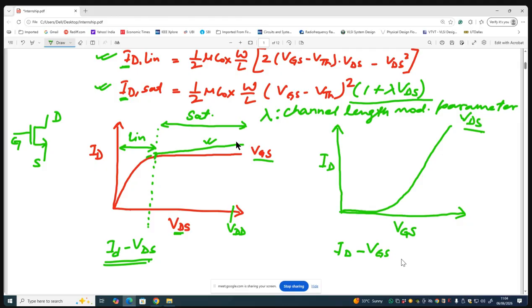And if you see the current equation, the red part of this current equation, we are assuming that the effective channel length remains constant irrespective of VDS. But as we just saw, in reality when VDS is increasing, the depletion width at the drain channel junction increases. The junction is reverse biased. Do you agree? The drain body junction is always reverse biased. Say yes or no in a MOSFET.